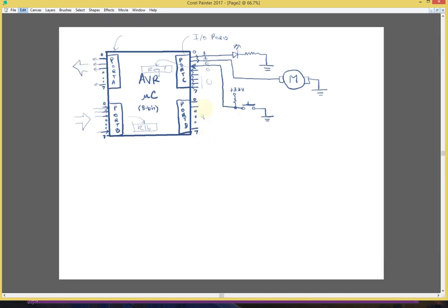Okay, now if I wanted to read port C, which has a mixture of some of the pins being outputs and most of the pins being inputs, you can still read it. What you have to do is basically read into R16 the value in pin C. Again, even though we have outputs and inputs, you still read via the pin C name, the pin name of the register. And then all of the 8 bits are going to be set.